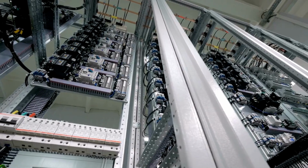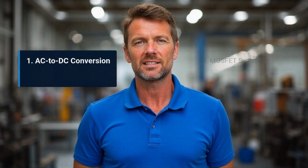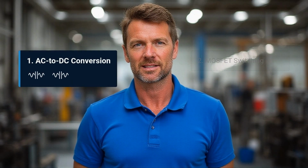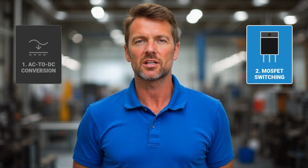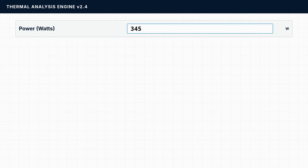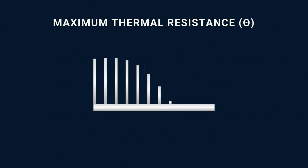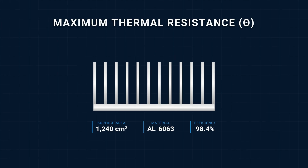It handles the two biggest heat sources in actuator control systems. First, your AC to DC power supply conversion losses. Second, your MOSFET switching losses in PWM controllers. You plug in your values and it gives you exact watt figures, BTU per hour conversions, and the maximum heatsink thermal resistance you need to keep everything alive.